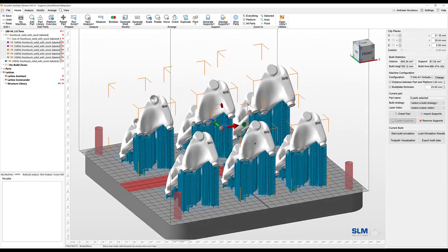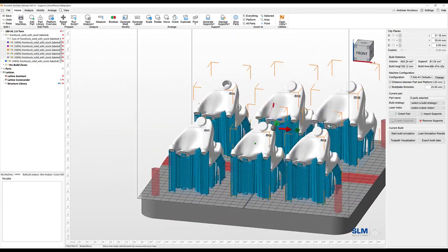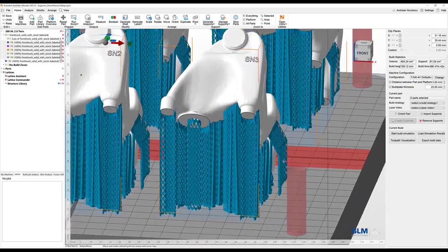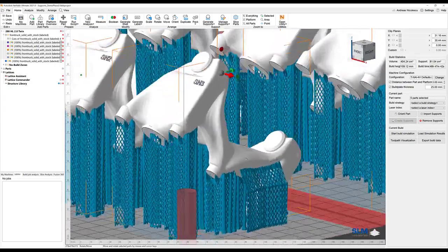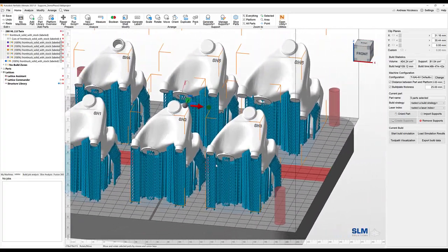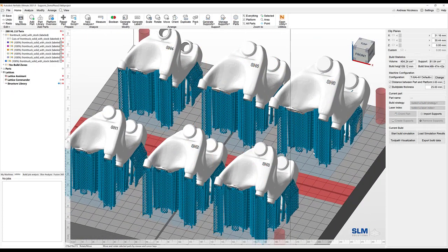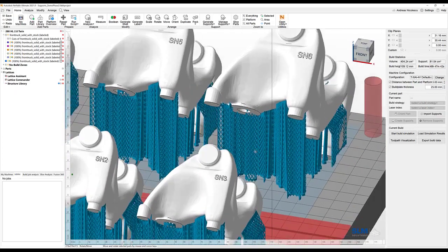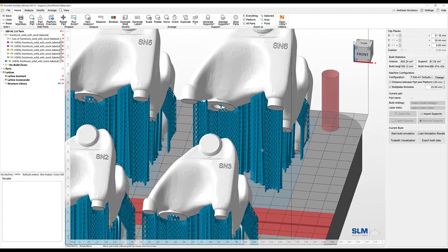Now the support should be adopted perfectly, and as we can see, the parts also obtain the manual improvement, the manual angle supports as we go. Should it not fit on the first try perfectly, as we can see here with the parts that I have scaled up a little, we can once again refresh the support also out of the Manage Support area, and then the support should be placed accordingly.